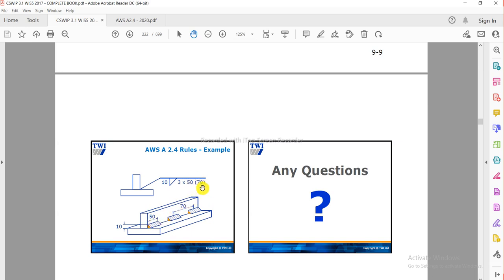And what does E stand for? As I told you earlier, as per the 22553 European standard, the gap is the length between two consecutive weld elements. In American standards, E means the pitch is not an adjacent gap but a center-to-center gap: the center of this weld to the center of this weld.